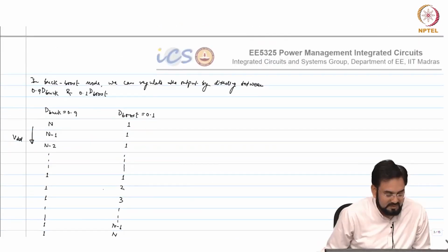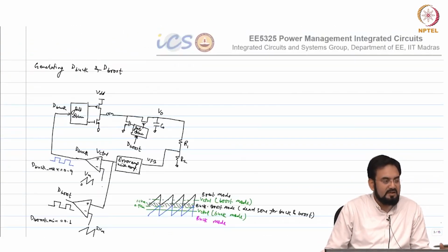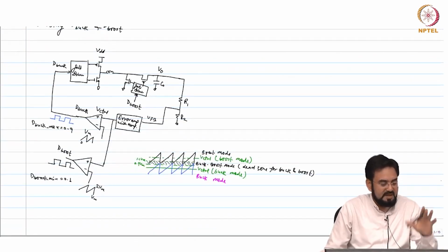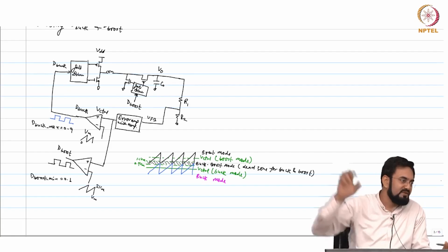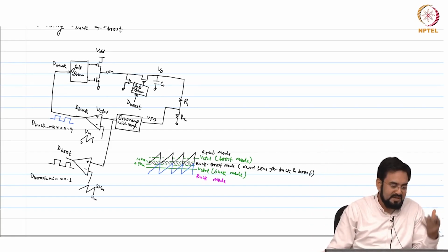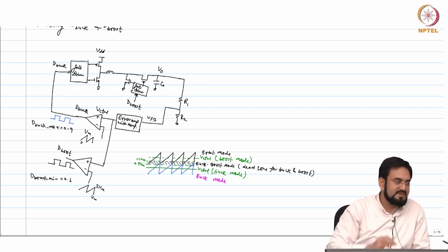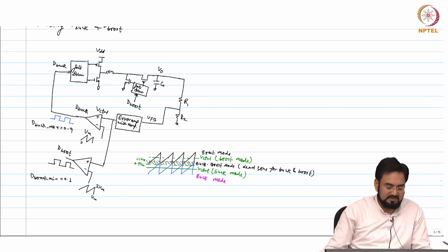Otherwise, if you want to do it in analog, then the only option is you leave it on its own and your loop will recover, but then you have to live with that transient, or you make your loop faster, or maybe find some way to compensate, like feed forward compensation or anything to correct the duty cycle. You can do that also.